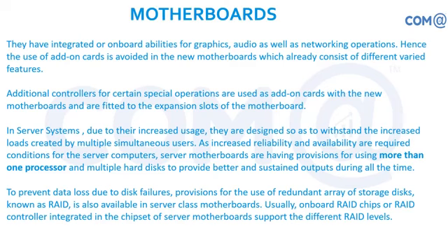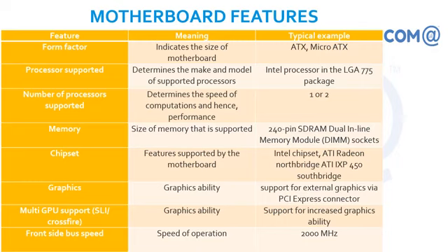Normally in the desktops we'll be having IDE connector. In servers we'll be using RAIDs because we need to connect multiple hard disks at a time, and we need to have data backup also in case of any hard disk crash or any emergencies. So we'll be having RAID controllers, and we'll have multiple hard disks connected into the server. So it will be supporting that facility physically as well as logically. That is the difference between a normal motherboard and a server motherboard.